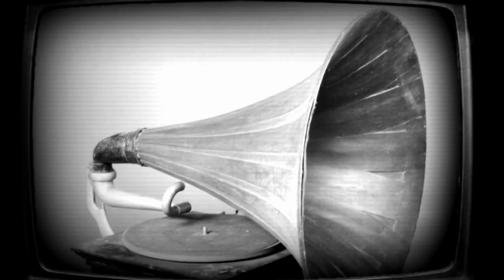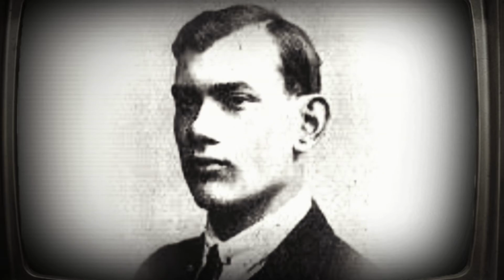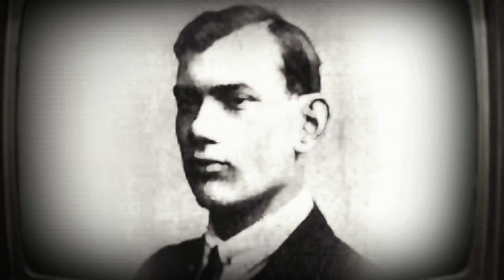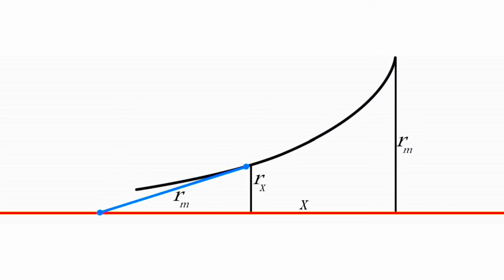It seems the horns on the old gramophones are a Tractrix curve shape. Today, we owe this great horn to the efforts of Paul Voigt and Dr. Bruce Edgar. In this horn, like spherical ones, the side view is formed by moving the fixed radius, Rm, on a horizontal line, but its flaring speed is lower than a spherical horn, and it cannot fold on itself.